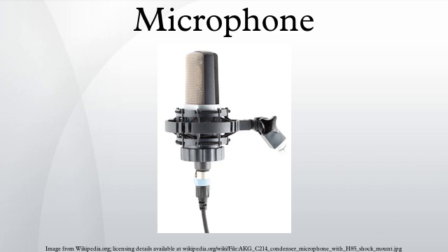Low-impedance microphones are preferred over high-impedance for two reasons. One is that using a high-impedance microphone with a long cable results in high-frequency signal loss due to cable capacitance, which forms a low-pass filter with the microphone output's impedance. The other is that long high-impedance cables tend to pick up more hum as well. Nothing is damaged if the impedance between microphone and other equipment is mismatched. The worst that happens is a reduction in signal or change in frequency response.